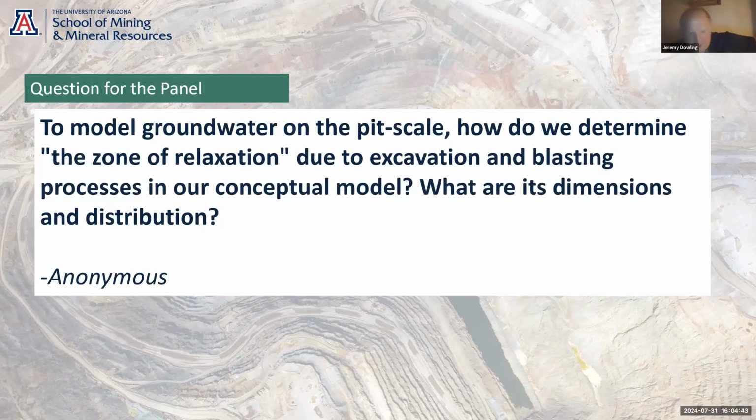I think there's a few sites that maybe have tried looking at some empirical things. Horizontal drain drilling maybe can somewhat infer rock mass quality at depth, just in terms of the drilling performance. And then there's a few mines, I think, where there are tunnels, old underground mine workings and tunnels close to the pit slopes, where maybe you can see deformation in the tunnels that may be related to the pit slopes.